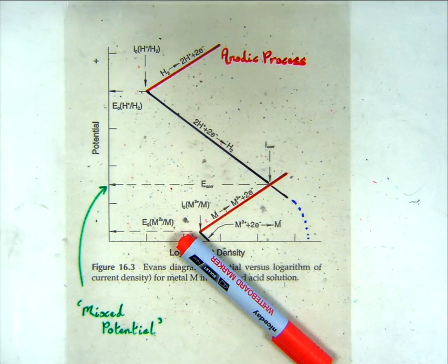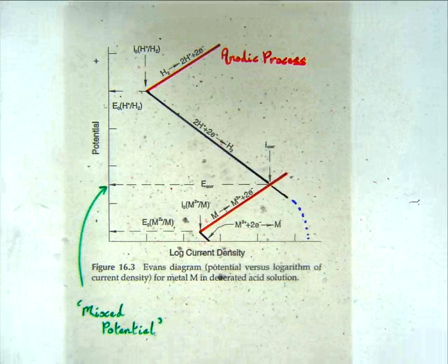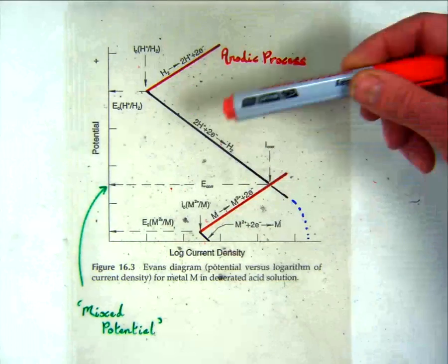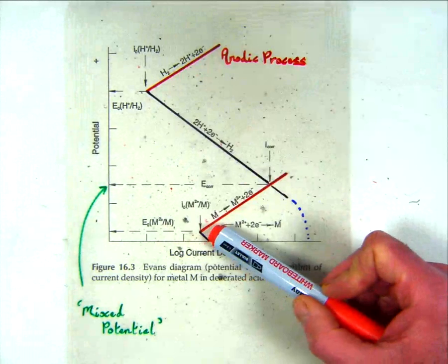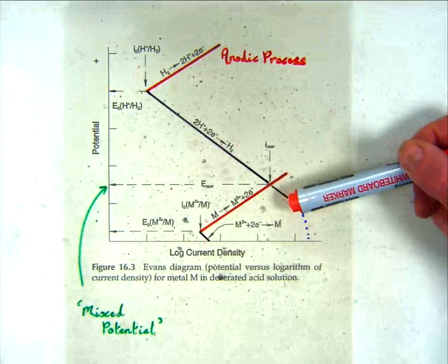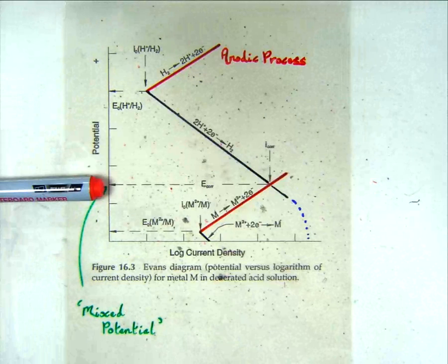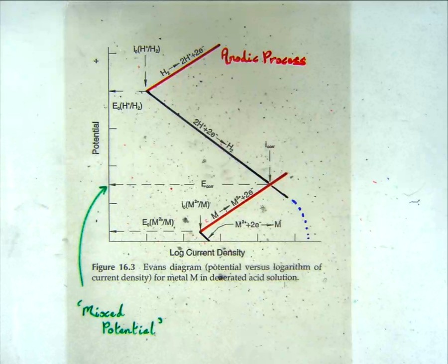And the new mixed potential is this one here. So, given some thermodynamic data, you can work out new values for different combinations of electrodes, or different combinations of reactions occurring, anode and cathode if you prefer. The intercept between these two lines is the new free corrosion potential for the new cell.